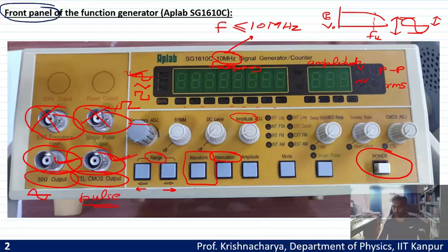You see these four displays over here written as 0 dB, 20 dB, 40 dB, and 60 dB. 0 dB means there is no attenuation. If you press this button once, this light will be switched off and this light will switch on, and you will read that 20 dB is illuminated, so you understand that now you are using 20 dB attenuation.